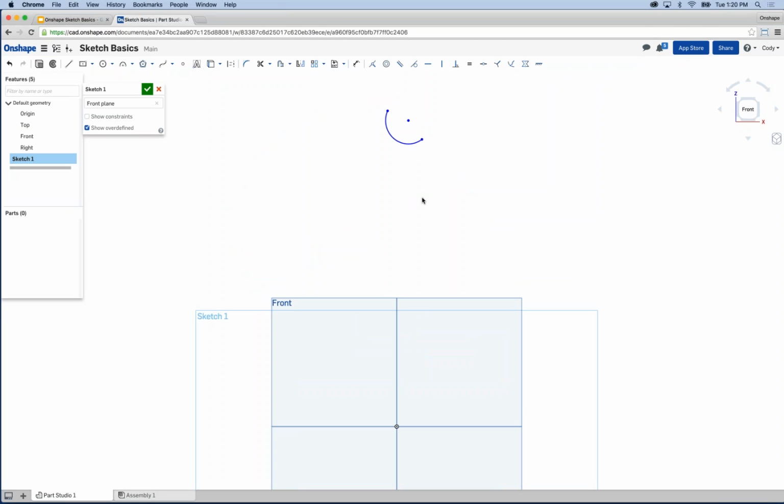Again, useful if you're trying to constrain the geometry, of these points, for instance, to other sketch or model edges, or whatever it may be. So it makes it easy to attach references. Now, in my case, we have a 3-point arc, but we also have a tangent arc, and a tangent arc is a very popular command. However, it's worth pointing out you can't simply create a tangent arc in space. Tangent arcs must be tangent to something.